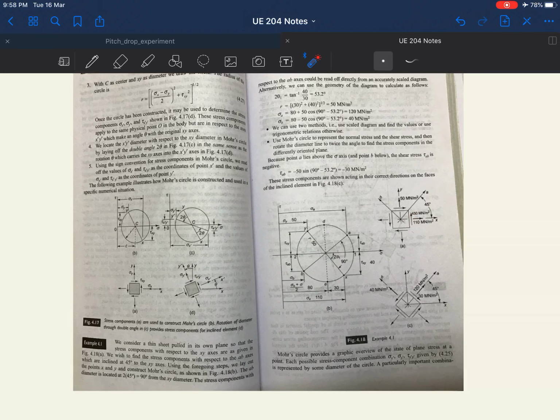They've given a cube, and they've given you these values, 110. There is a shear stress of 450, and the shear stress here again. Sigma yy is given as 550, and they draw the Mohr circle. Since this is positive, it has to appear here on the negative side.